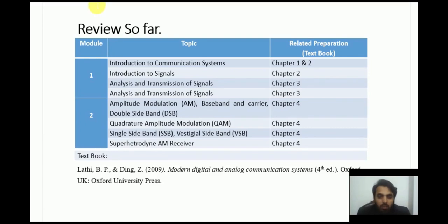Next we moved on towards essential bandwidth. Any time-limited signal would have an infinite bandwidth, that is an absolute bandwidth. But we are not really interested in absolute bandwidths. We are interested in something like 3 dB bandwidth, or some percentage of bandwidth. That is the essential bandwidth. The leakage or spillover is governed by regulators. For example, in Pakistan, we have PTA that defines the power limits that they can tolerate beyond what you have purchased. On similar lines, we moved on towards energy spectral density and power spectral density.